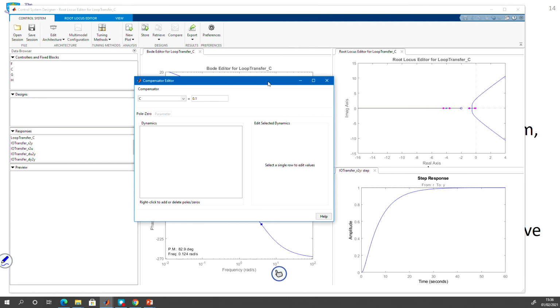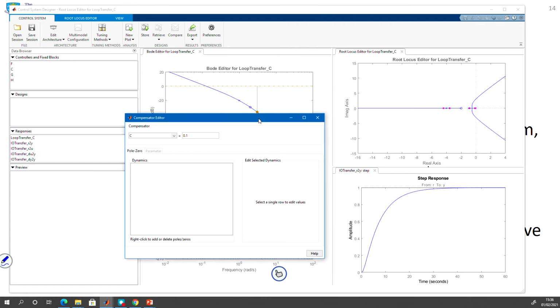So I can actually get different values for closed loop poles by changing k. I can try 0.5 and you'll see they move. Or I can try 2 and you can see they move. So basically, as I change the gain, the closed loop poles change, and you'll see SISO tool is also showing what's the corresponding closed loop step response down here.